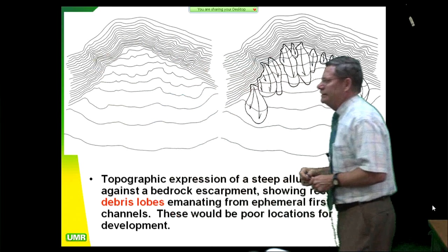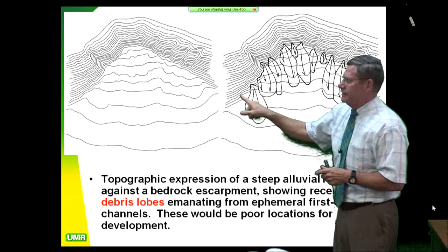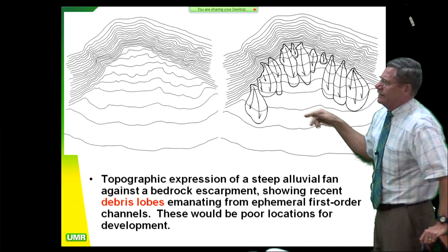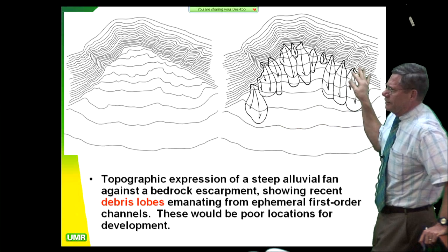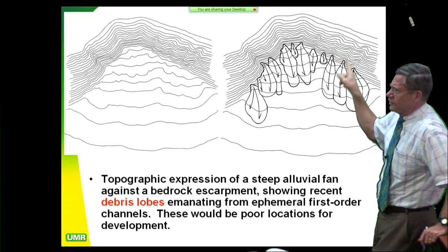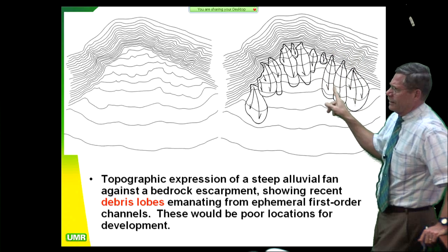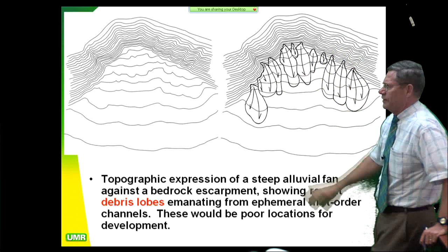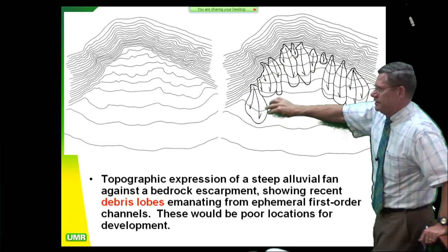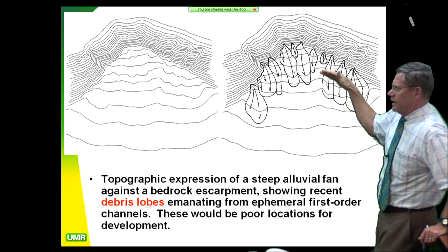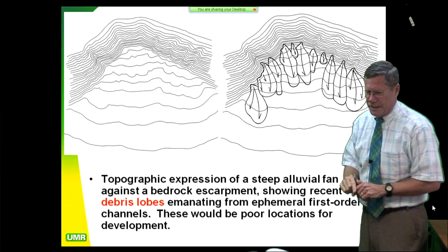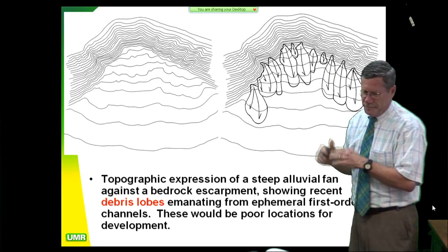I said, well, you can always have rock falls, but when I look at the air photos, there's your debris flows that you've had in the previous 100 years. Some just beautiful debris flow fans come out of these little first order and second order drainages. And of course, these people didn't like me very much because I was saying, well, put your parking area up in here, but put your houses down here. Or if you want to put your house up here, you got to put a big, huge impact wall behind it, like 3 foot thick reinforced concrete and earth sheltering and so on.